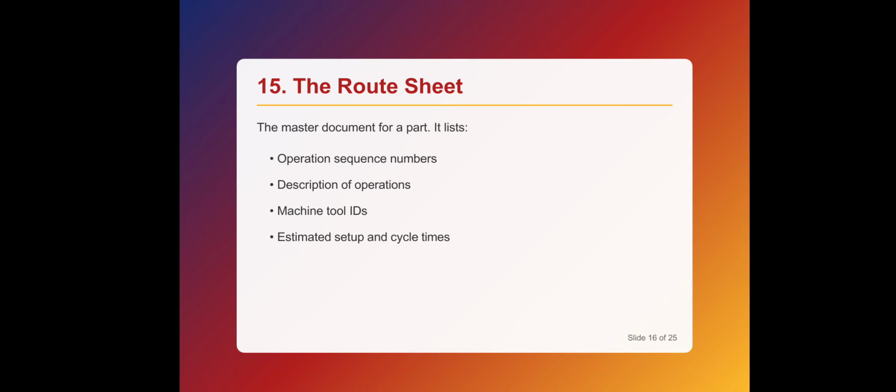So the approaches involved in process planning are mainly manual process planning, and the second one is computer aided process planning, that is CAPP: retrieval CAPP system and generative CAPP system. Those are the two important approaches to process planning.